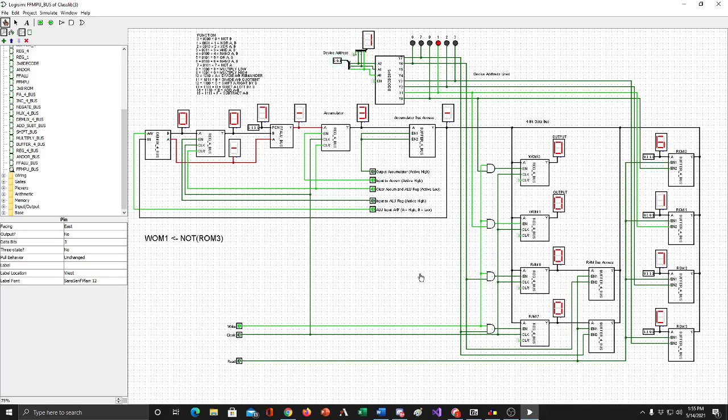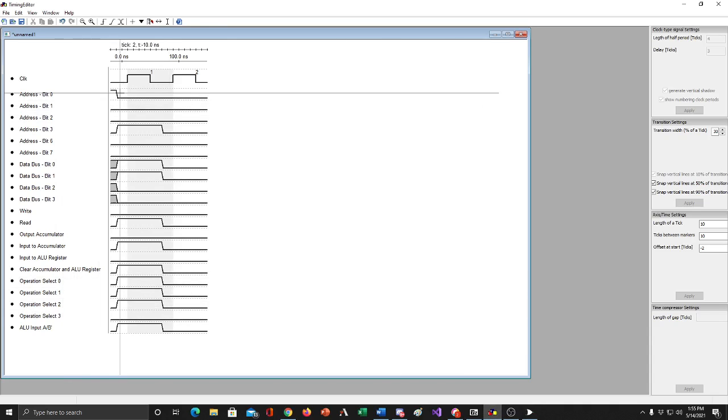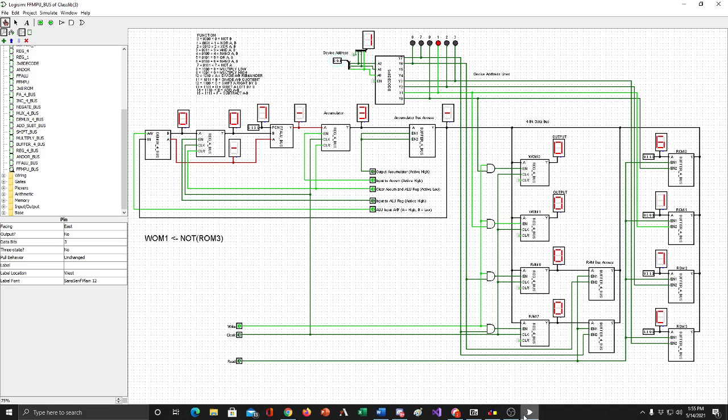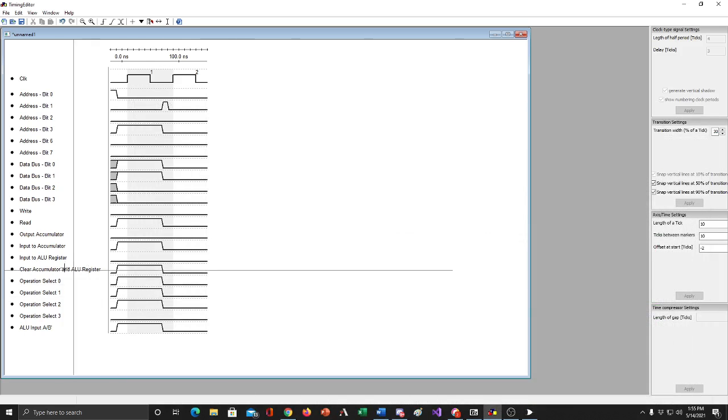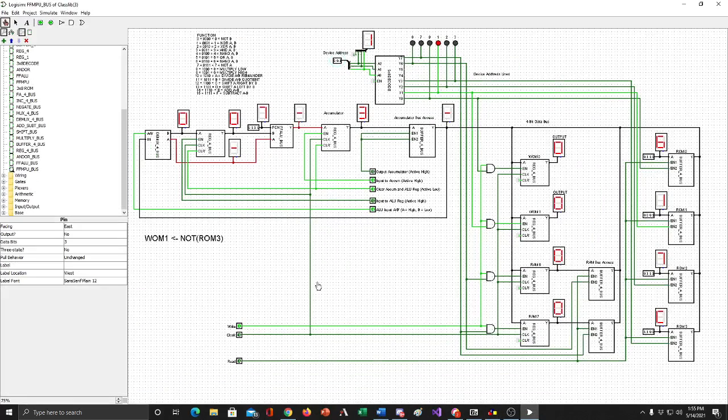So I'm going to stop moving things for a moment and make sure that this is caught up. So we changed our address marker. It stops being 3, and it will begin to be 1. So I'll bring that up there. The write line is high, so I will activate the write line there. So let's see. So we changed those. Once we took the read line off, well, we're going to make a couple more modifications. So I'm not going to put in the data bus until I finish changing the control lines.